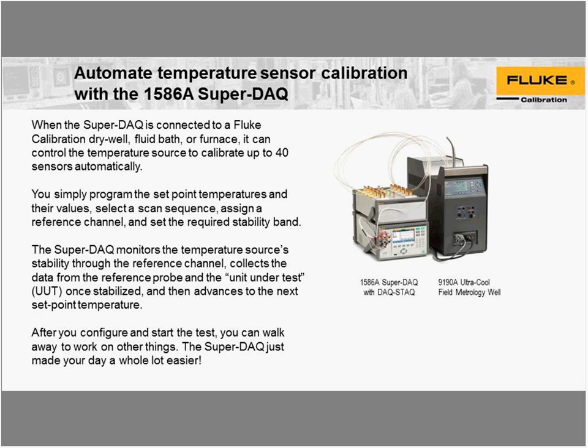In addition to that, it has programmability where you can simply set up a table. So in the example before, we could load the unit with a few probes and our reference, and then tell it to go to these different test points. The unit would collect the data, and then we can extract it via thumb drive off the front panel and go back and calculate the coefficients for the units. So again, just another innovation depending upon what your business entails.